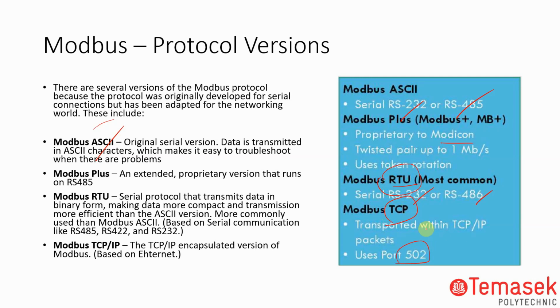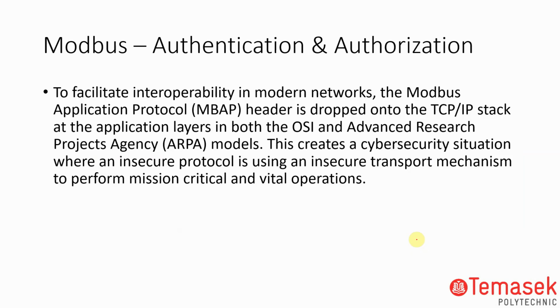Okay, and it is possible, as I mentioned early on, to put in TLS, basically the security for Modbus. Because people have already done it, because it's open source, so it is highly possible to do it. The issue is not about whether it can be done or cannot be done. The issue is whether vendors want to do it or not. The main part is whether all your end device vendors are willing to spend time and effort to do this. That's all. It is highly possible to do this. The code is available. Just whether they want to do the implementation or not.